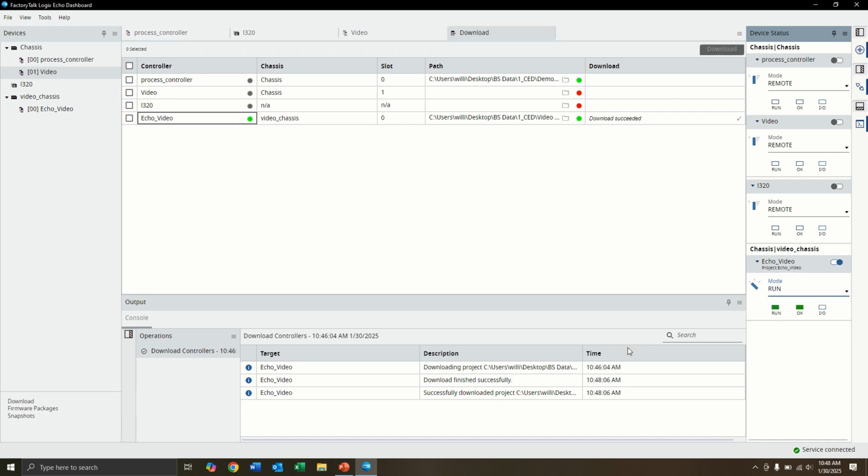So we never actually had to open Studio 5000. From here, we could attach an HMI to this PC and test. We couldn't edit without opening Studio 5000, but we could test the program without ever actually having the software. But for those of us that are used to downloading to a physical controller with our software, that is an option too. We'll go through that next.